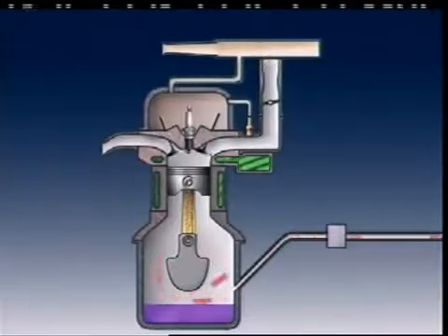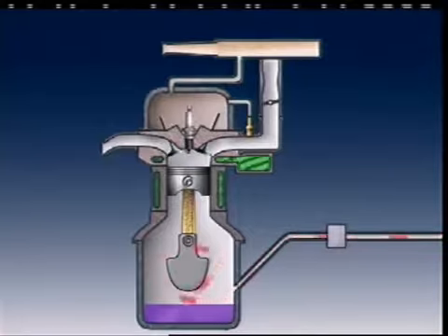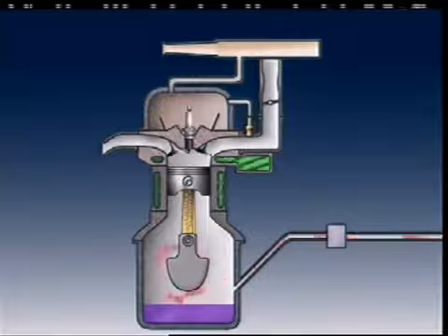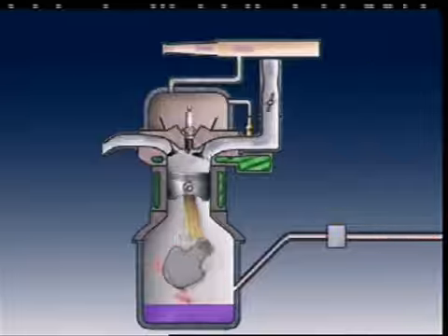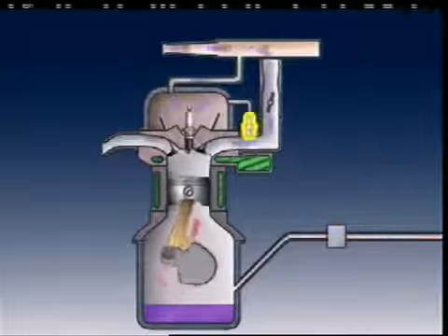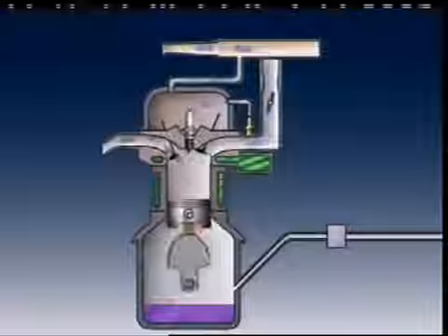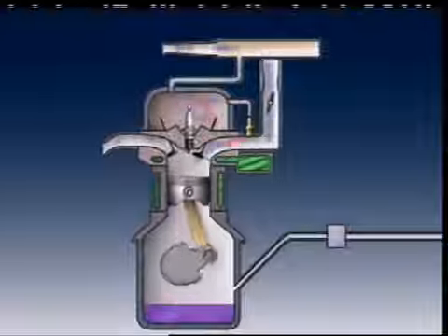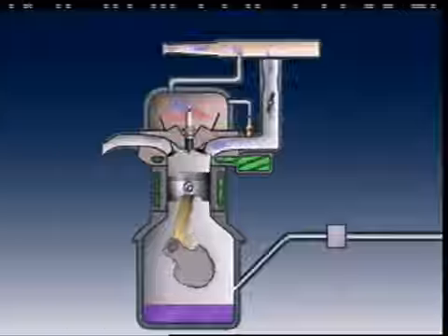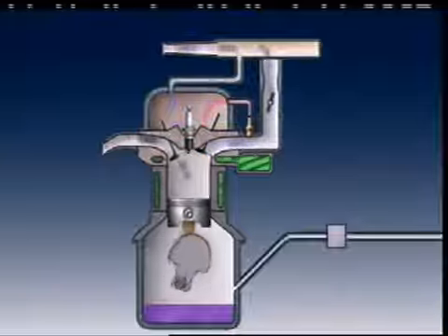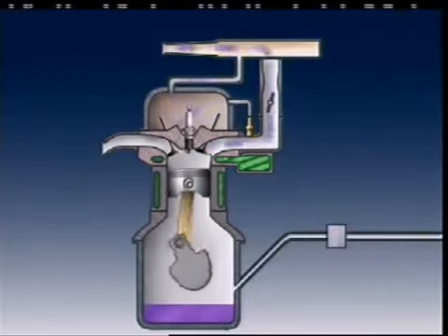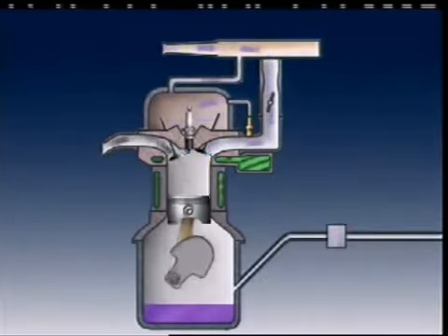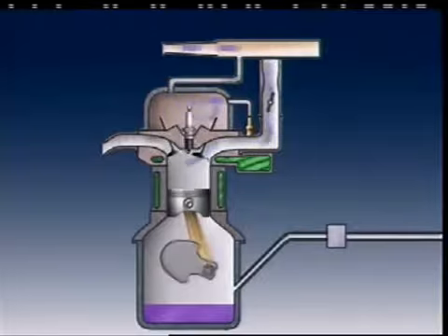Some vehicles use the engine crankcase. When the temperature of the fuel in the tank increases, fuel vapors are forced along the vent line past the liquid check valve and into the crankcase. When the engine starts, the positive crankcase ventilation system flushes vapors out of the crankcase and into the intake manifold, where it joins with the inlet air-fuel mixture. Once in the inlet manifold, the vapours are drawn into the engine where combustion can convert them into carbon dioxide and water vapour.